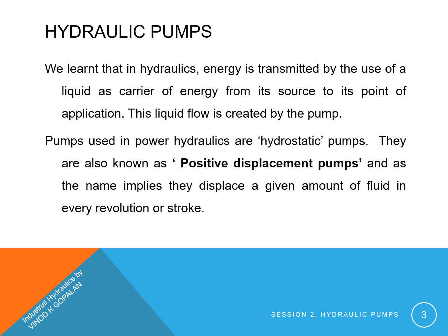We learned that in hydraulics, energy is transmitted by the use of a liquid as carrier of energy from its source to its point of application. This liquid flow is created by the pump. Pumps used in power hydraulics are hydrostatic pumps. Pumps can be classified as hydrostatic and hydrodynamic pumps.